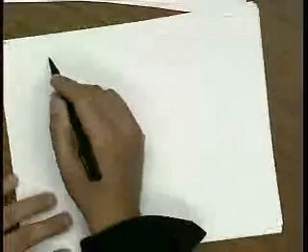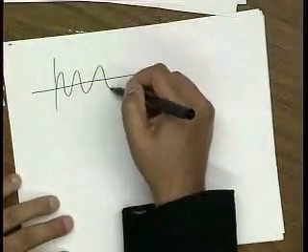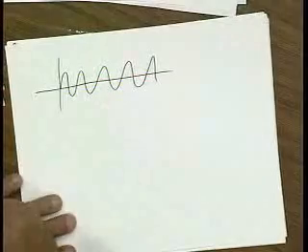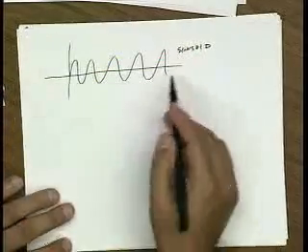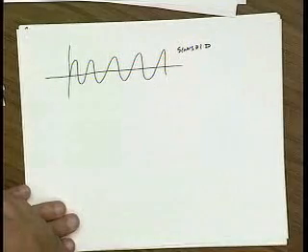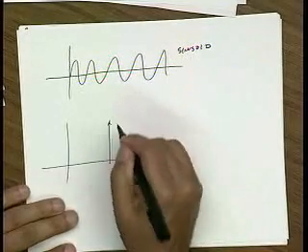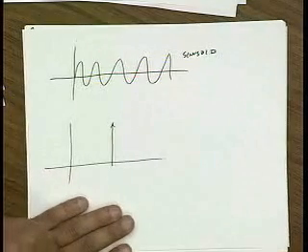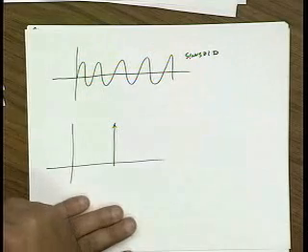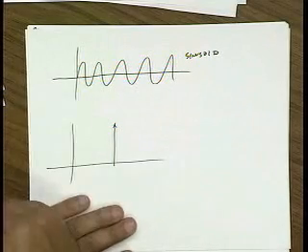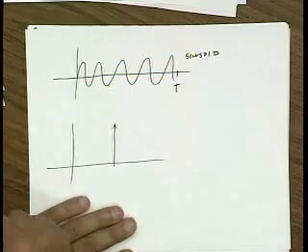Okay? So the easiest way to see it is imagine you have just a sinusoid. And you want to take its FFT, right? You know that the ideal FFT would give you basically a spike, a delta function. But nobody has an infinite amount of time to run simulations, so what you do is you run a simulation that's t long, right? So I simulate up to time t.